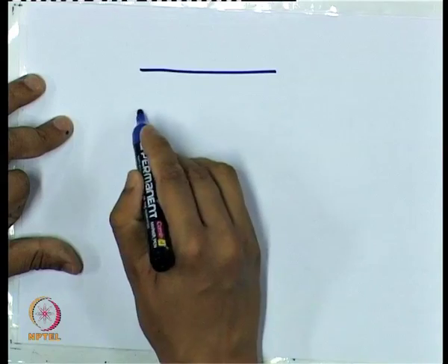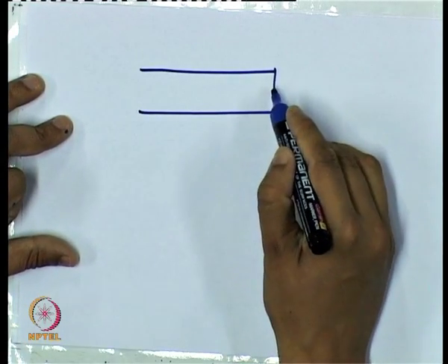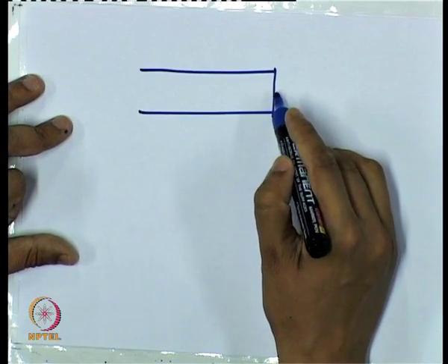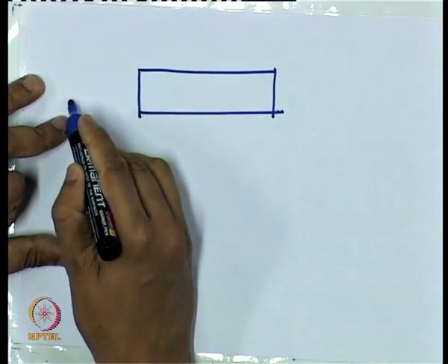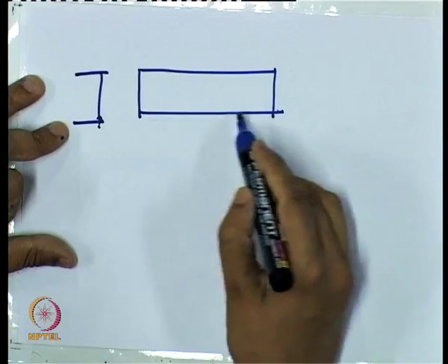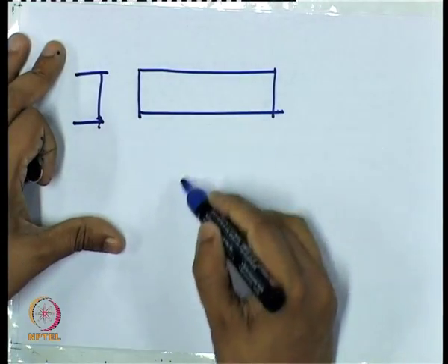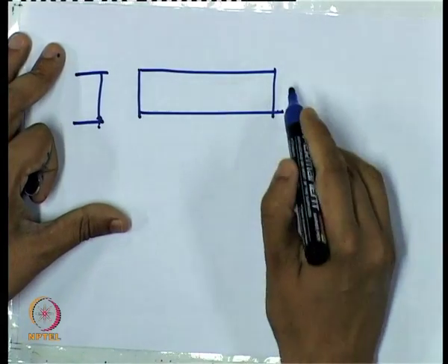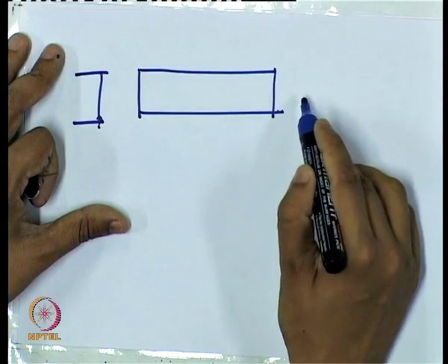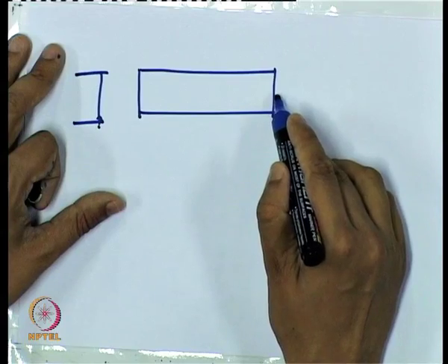So, we saw how to implement a series resonator in shunt. Now, if we want to do the other way, that is, implement a shunt resonator in series, then that becomes a problem, because shunt resonators using, say, an open stub are difficult to realize. Why is it difficult? An open stub resonator always has one end open, since it is an open stub, and the other end can be either directly connected or gap coupled. While this can be easily realized in shunt, because in shunt this end will hang from the circuit, in series it is necessary that something at the other end is connected, which is not possible because this is an open stub, it has to be open.